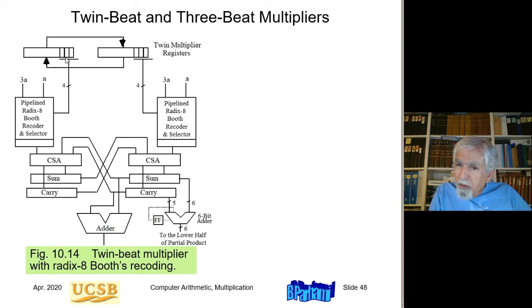So 3 bits of the multiplier are handled in the high part of the clock, phase 1, 3 bits in the low part of the clock. So this carry-save partial product is given to this half, which takes the next 3 bits. So these 2 registers are 3 bits out of phase. So this is, let's say, if this is x0, x1, x2, this is x3, x4, x5, the next 3 bits to be handled.